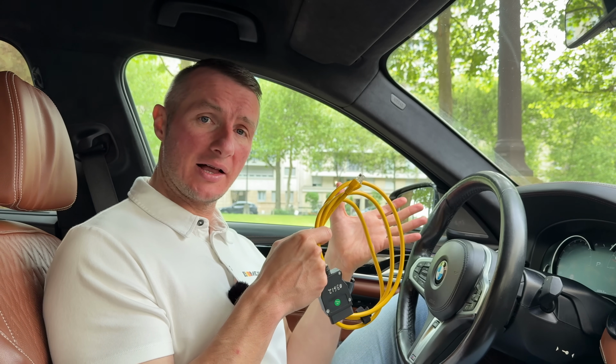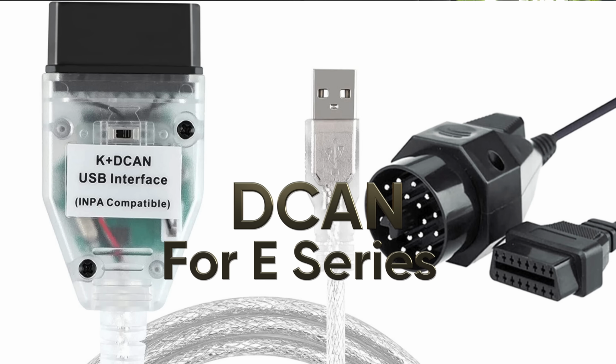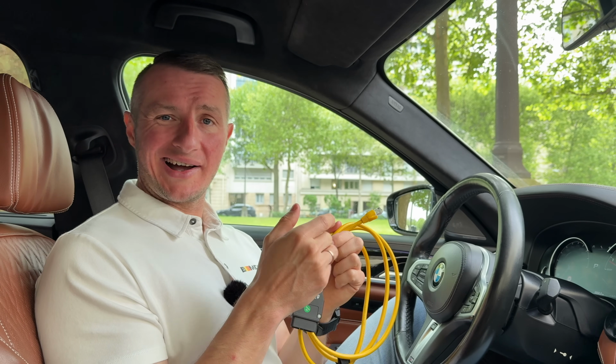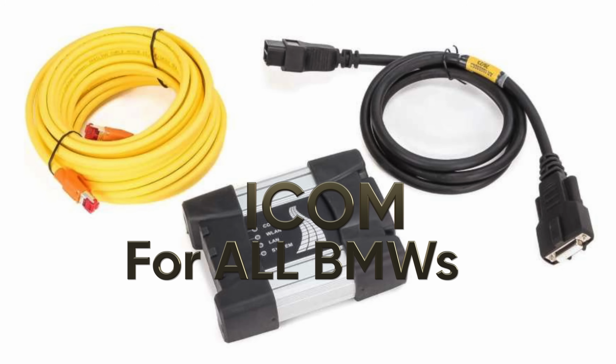If you have something else, for example older, the E series, then you'll require another interface like a DCAN cable or the ICOM. Of course, the ICOM is the official BMW hardware. It looks like that one. It can be used to work with all the BMWs, E, F, G, I, you name it series.